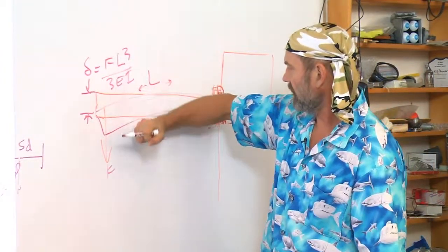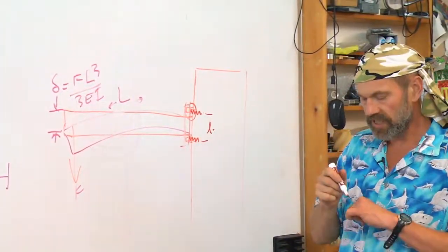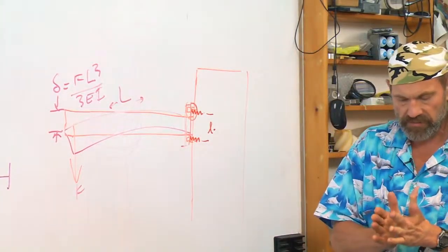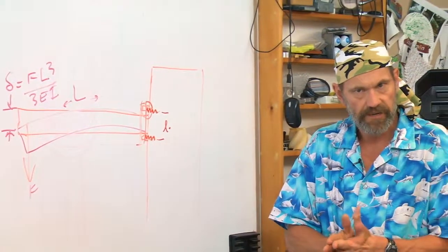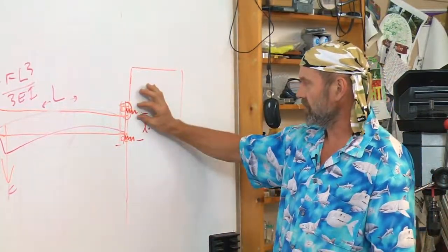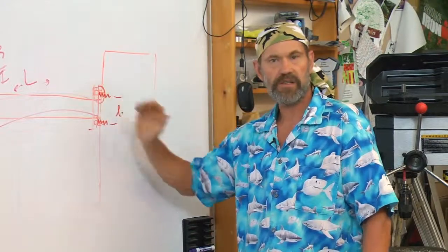So I'm going to have an angular motion due to this spring motion at the base. So the same type of analysis in terms that you would do to calculate just the axial stiffness of a bolted joint applied to these 2 points is now used to determine the deflection at the top and the bottom, and hence you can figure out the tilt of that joint.